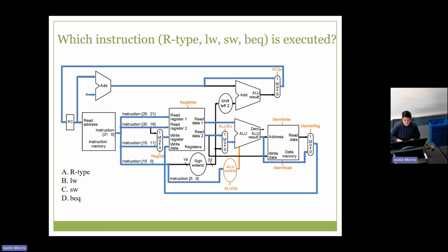From the view, I saw that the instruction lines didn't overlap the write register RD, and that's going to the mux, therefore immediately I can tell it's a different type of instruction. Then as we go through to double check it, instruction 5 to 0 goes to the ALU control, which is the funct code, which is used in the R types. And looking at that ALU, the ALU result is not going to memory, going straight through the mux back to write data. So we did an R type operation on it.